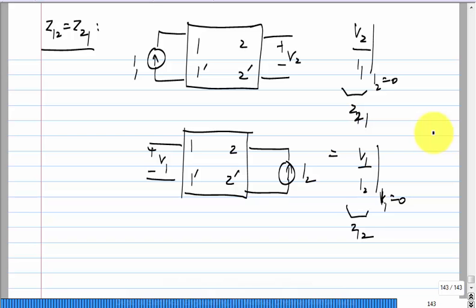So, again, that is in a circuit, if you have a current source and you have to measure a voltage here, you have to consider, maybe it is easier to apply a current source here, measure the voltage here, the ratios will be the same. Okay. If it happens to be easier to work the reverse problem, that is a useful technique. Whether it will be useful or not, I don't know. That depends entirely on the circuit.